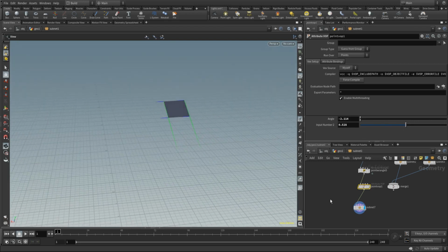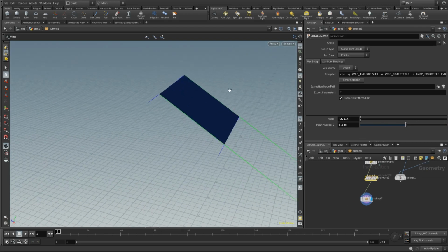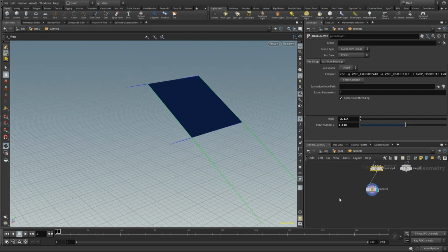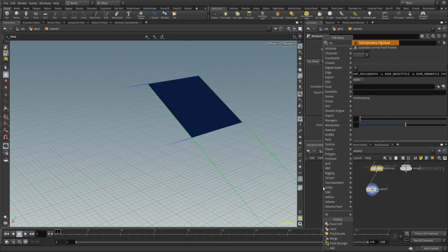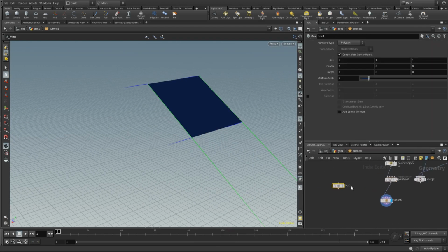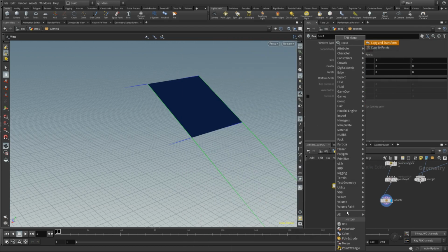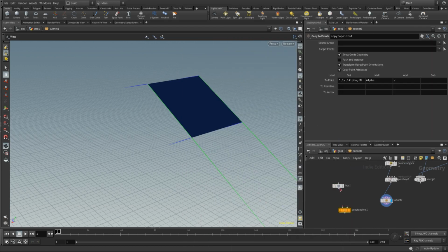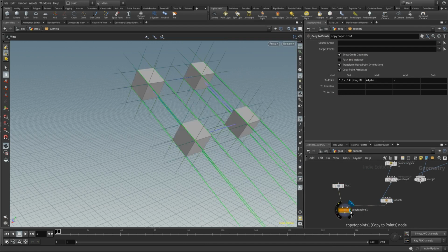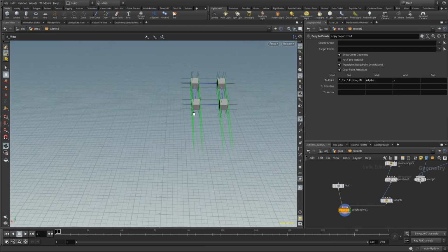As easy as that. And the cool thing is we have some nicely oriented values, you see the normal and the up, those are orientation attributes. So we can also immediately use them to, for example, place your objects. Because I don't know what you want to place. I'm going to place, that's a little bit heavy. Let's just place a box right now. And this box is going to be a small box, and I will, with a copy to points, place it on top of the corners of the roof. There we go.